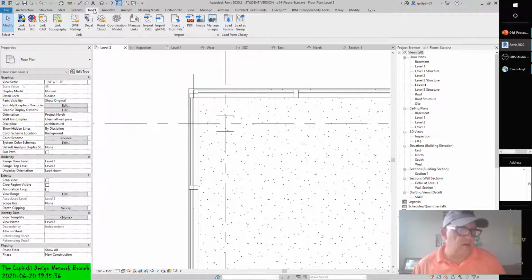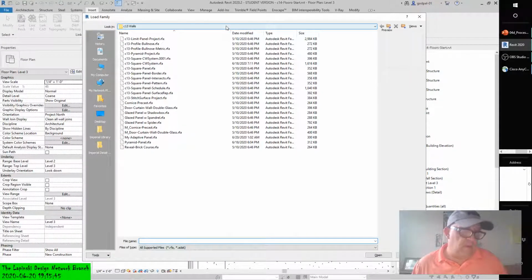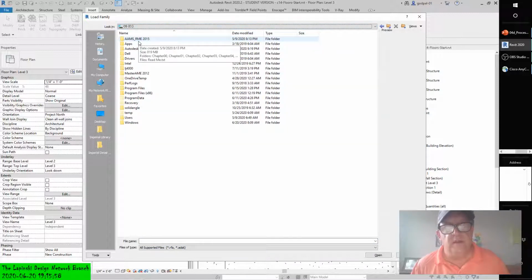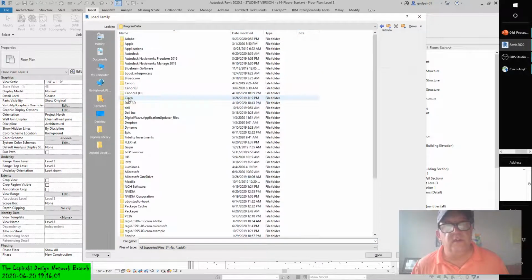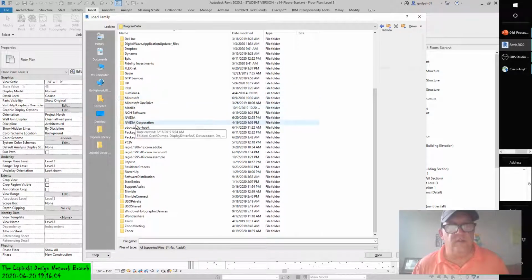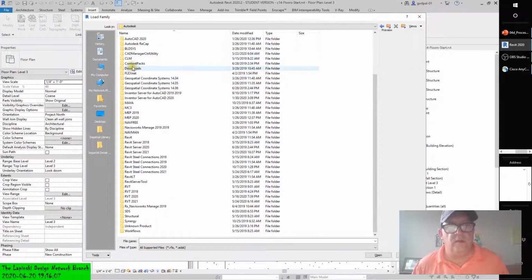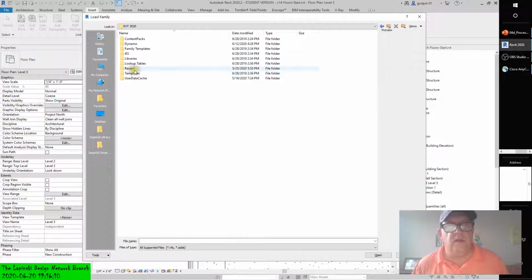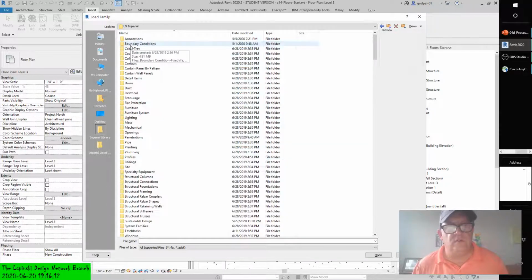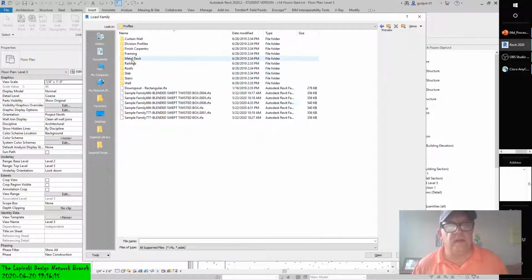So if you don't have a structural deck profile loaded, finish this floor by selecting Edit Mode, then select the Insert tab of the ribbon and click Load Family. In your default Autodesk content library, you'll see, this isn't the default library, remember, it's in the root directory. It's under the program data, which is hidden. And again, I can tell you this a million times, it's under Autodesk, and it's under RVT 2020, and libraries, US Imperial, profiles, metal deck.